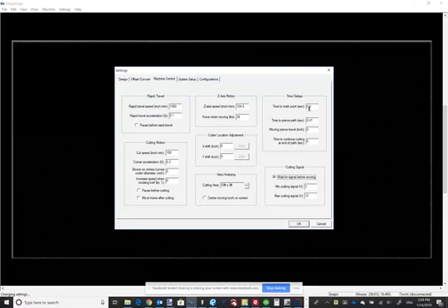So on the pierce, time to pierce, if you don't have either at least basic height control or advanced machine control, you will not have this cutting signal box, and you'll have to add time into the pierce box, the time to pierce, to allow for the pre-purge on the Hypertherm for it to work. That creates trouble. So that is from basic to advanced.